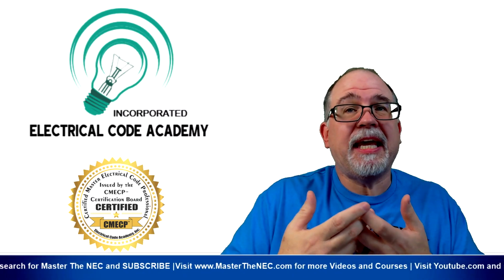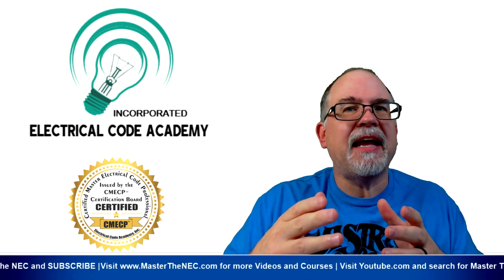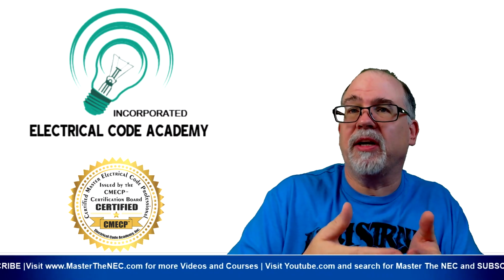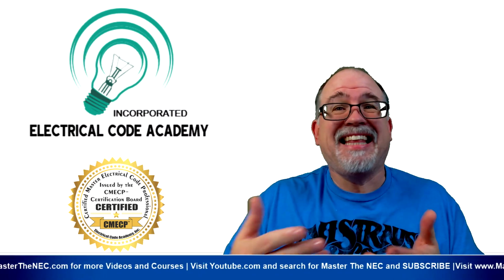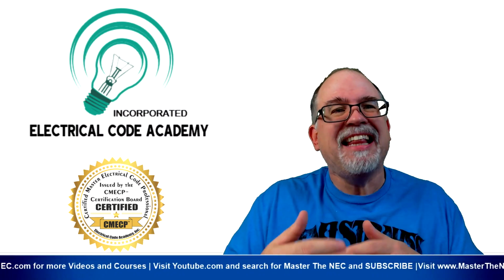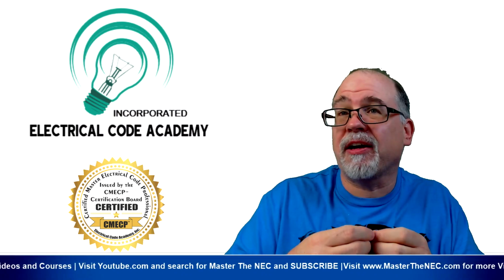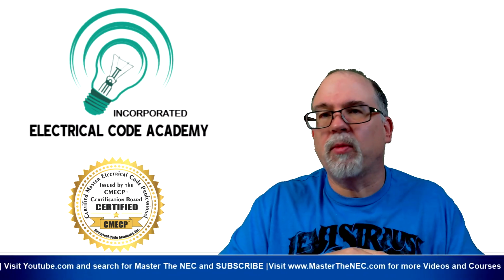Because there is an application where that 250% might be utilized. But for everyday applications, except for an exam, you're not going to use the 250%, because that's an exam question. In reality, we're probably going to use 125%, unless, for example, that can't handle the inrush of the transformers. Then we can go up to 150%. And again, we've got to keep an eye on our conductors to make sure they're protected. All right. But there are some rules that we apply to that.